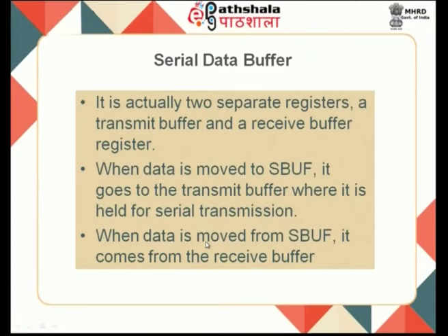Then the next important thing which we will be looking at is your serial data buffer. That means, if I am looking at serial communication where the 8-bit data will be processed in the 8051 register processor, when we are using an input device which sends data as serial communication, that means 1 bit after 1 bit, then I need to provide an interface. The same way, if I am looking at an output device which reads the data only a bit after bit, then I need to provide a facility for that.